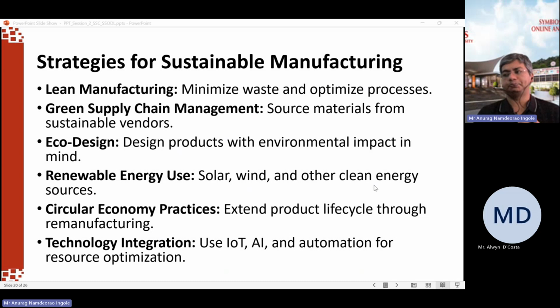And then you have VSM, which is value stream mapping. You define value, then map the value flow, then you reduce waste, and then you optimize again. It is the PDCA cycle, plan, do, check, act, a philosophy where you continuously identify waste, try to reduce it, again analyze your process, try to find waste and optimize your process. So that is one strategy which will help you achieve sustainable manufacturing.